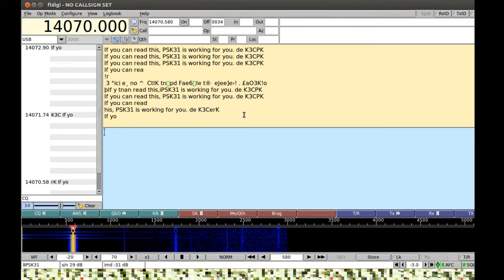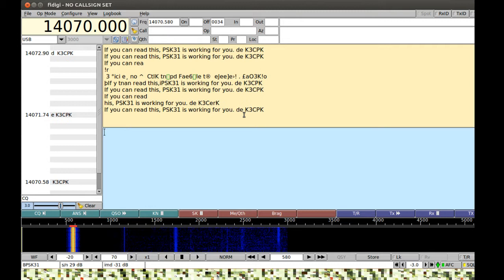What do these mean? So actually it'll break if there's a lot of signals in your waterfall. It'll scroll text of all the signals that it sees. Oh, I see. Go to FFT settings down here. Drop your FFT size way down.